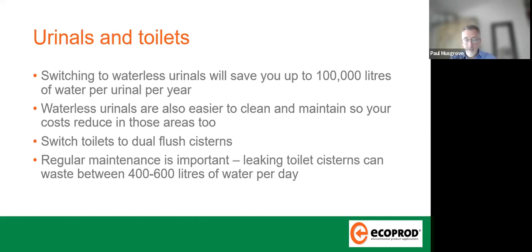When it comes to toilets, I think many buildings across the UK, both domestic and commercial these days, will look at dual flush switching, which typically provides a 6 litre and a 3 litre flush provision, which can be reduced to a 4 and 2.6, depending. The key thing is to make sure that the soil pipe is cleaned and nothing is blocking the water escape, going back to the waste.